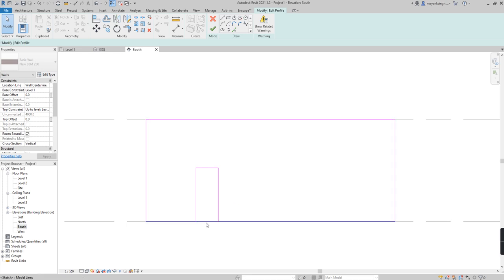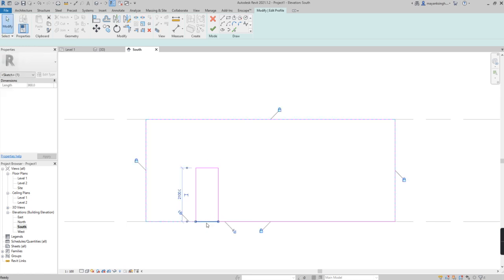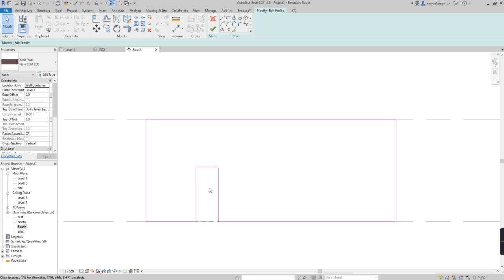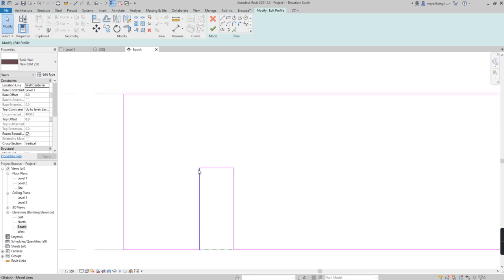There's these extra lines here. Now how do I split this? I can trim this or use the shortcut called split lines, SL. And I press SL and I make these two cuts. This separates out and this is there. Now this is not done. We're going to make another opening here, which is going to be 150 extended and 150 deep for the lintel.